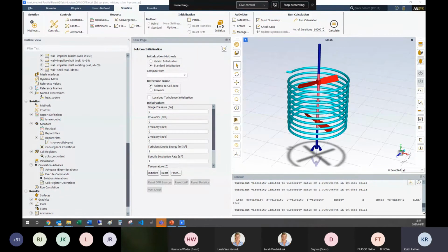So if I'm interested in the outlet temperature, I should monitor that and see when my outlet temperature is converged and is no longer changing. I can also add a criteria for convergence based on my monitors. So it's good to add monitors on 3D zones like average velocity, maximum velocity, average pressure, maximum pressure. Those are also good things to monitor.